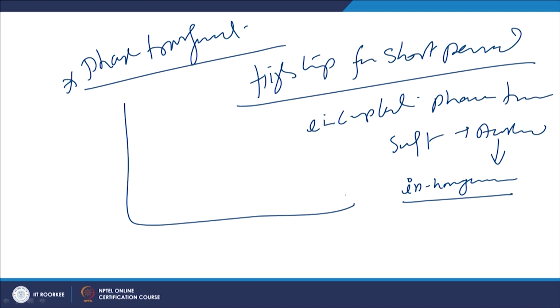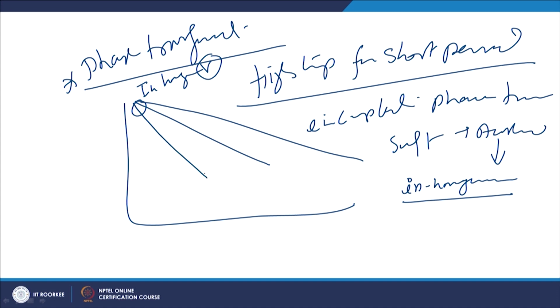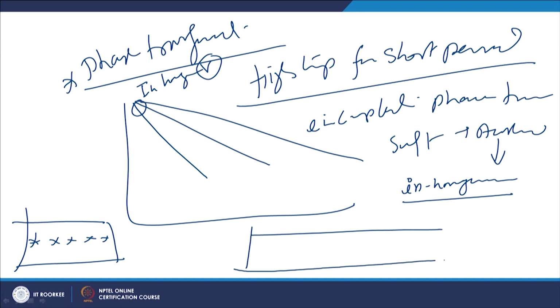So, if we see here, here we have the inhomogeneous austenite available for transformation, and it will be subjected to the different cooling rates as per the distance away from the fusion boundary. If the point is close to the fusion boundary, it will be experiencing higher cooling rate, and on increasing the distance away from the fusion boundary, the cooling rate will keep on decreasing because of the varying thermal cycles which are experienced by the weld metal.